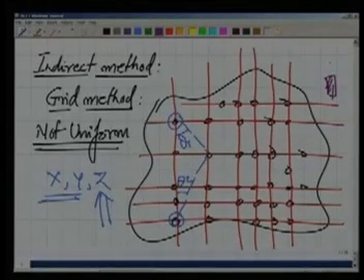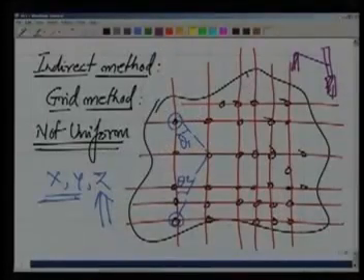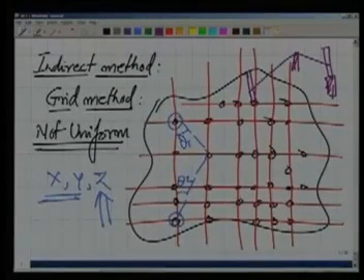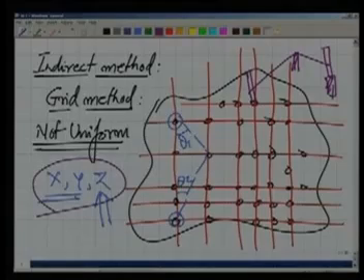Starting from the benchmark, keeping a staff there and keeping the level, it may be the dumpy level, it is leveled, so wherever we are rotating it, it will make a horizontal line of sight. So we keep putting our staff in all these points and measure the RLs. What we are achieving by doing this is the x, y, z of all these points.